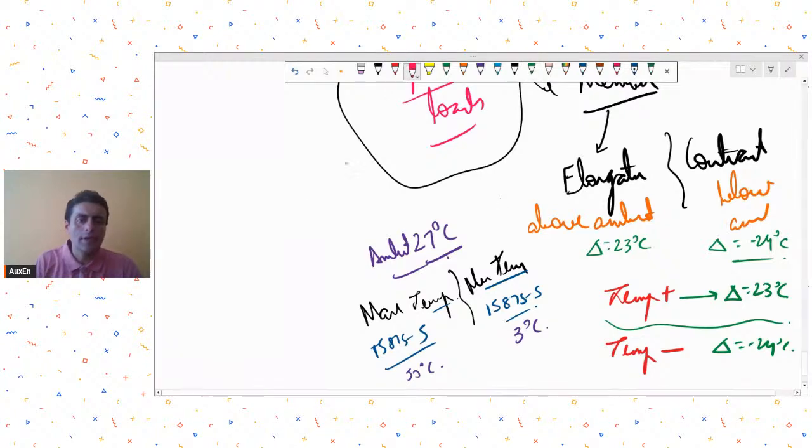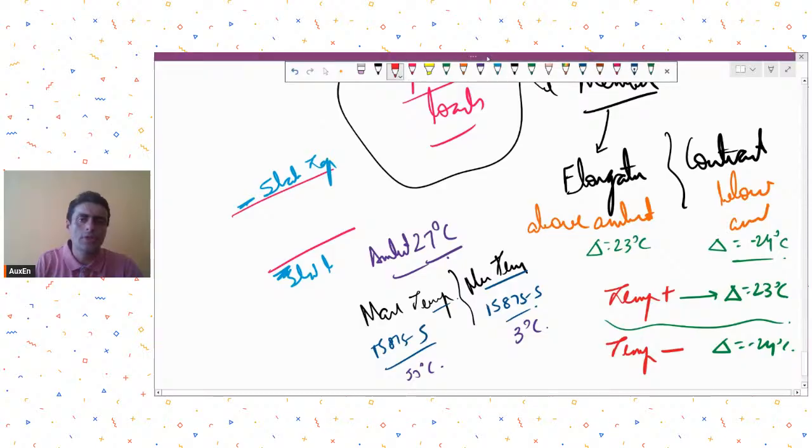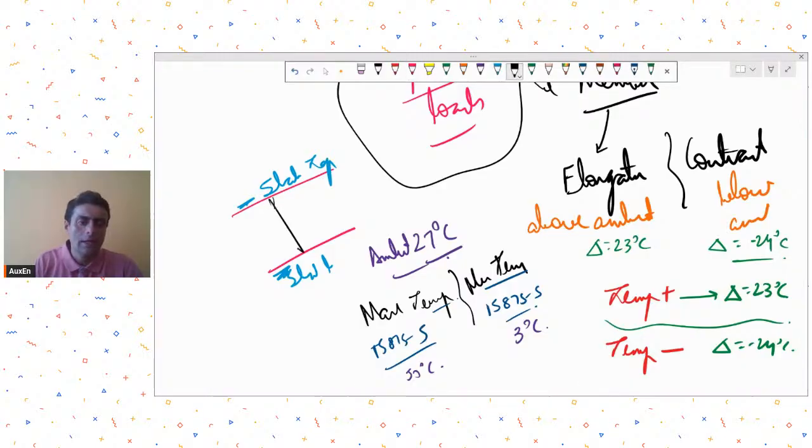There is a slightly different way. If it is a floor system, let's say this was a slab, this is slab top, this is slab bottom, and if there's a temperature differential between the slab top and bottom, then you have to give this temperature differential in the software, and it will calculate the restraining moment, shears, axial forces, etc. So in STAAD or in ETABS also, you can apply temperature loads on members or on your shell elements. Clear?